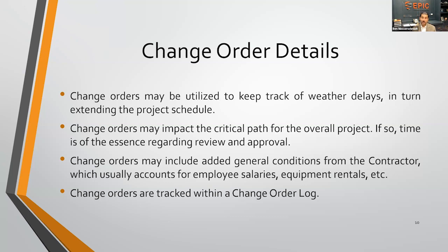On most AIA contracts, if that exists within this example, they will stipulate maximum timeframes for each entity to do their review and provide a response. And it is not going to be 2 or 3 weeks for either of those items. You're probably talking about anywhere from 5 to 7 days usually.